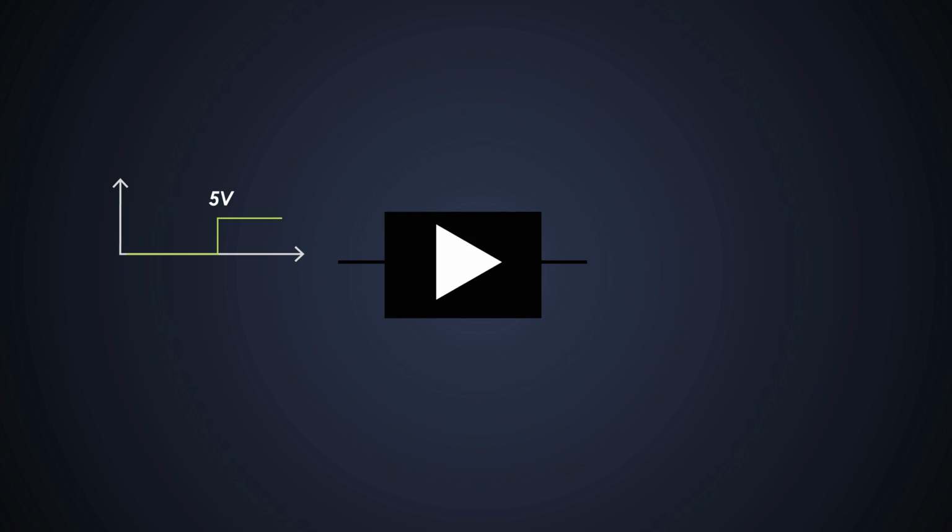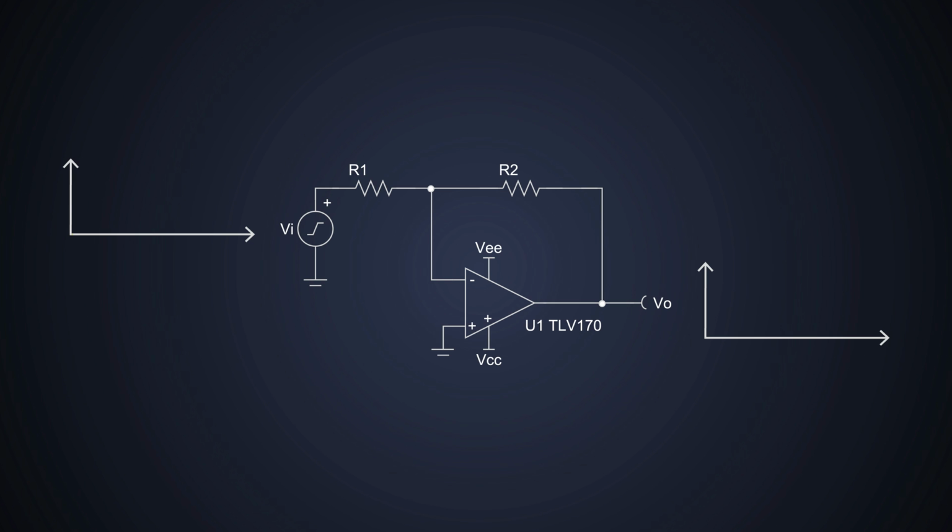Picture this. We have an input voltage of 5 volts, but we want to amplify it using the op-amps and get minus 10 volts as the output. This sounds a bit unrealistic, right? Well, not really. We just need an inverting amplifier. It represents the inverting output logic of this amplifier. It's like flipping the voltage upside down.